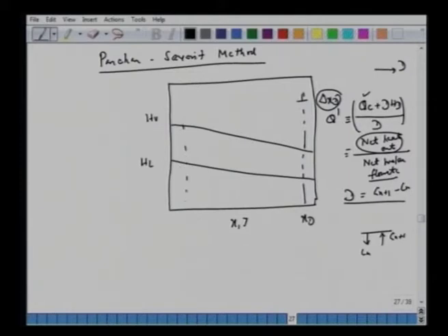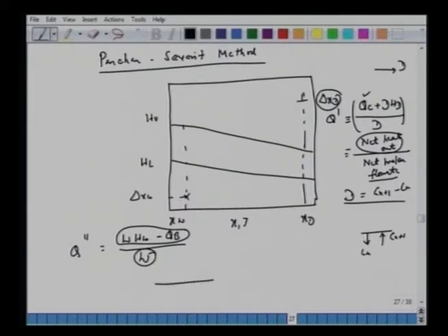Similarly, we did the same thing for the bottom product, where we had this xw, and we said that q double dash corresponding to this del xw point equals W hw, the enthalpy leaving the system, plus, here minus, you have this qb, you are giving the energy here, divided by this W. So same definitions: net heat out divided by the net molar flow rate W. So for any bottom stage we have G_m+1 and the liquid leaving is L_m, so the difference is the same as W here.